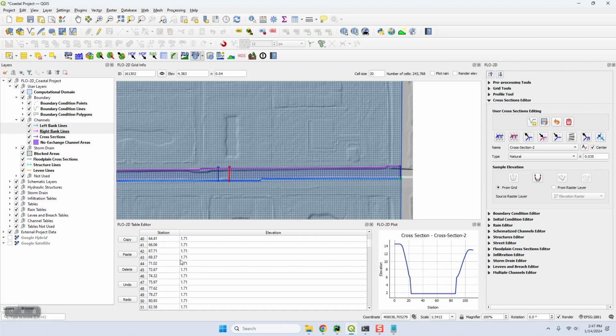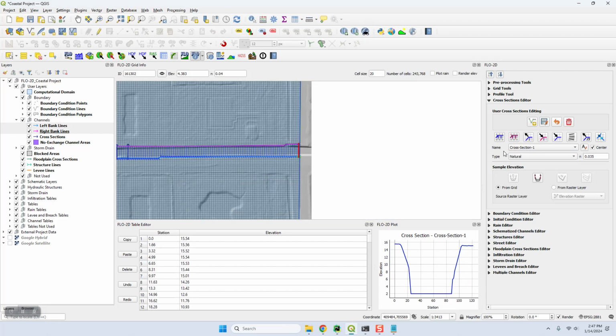this elevation is slope, and the elevation between these two means that this 1.91 is going to continue on through this little area right here, and there's not going to be a general downstream slope. It's just going to be flat for a while. So we can fix this in two different ways. I think the reason we're getting this error now is because I deleted a cross section right here to speed up the process so that this wouldn't take as long for you. But that caused this error.